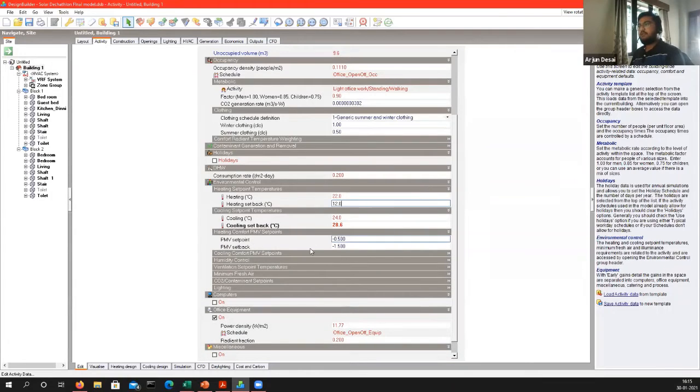The comfort set point: if you are aware of the different thermal comfort models, such as predicted mean vote, you can keep PMV as a set point. Your air conditioning set point won't work at that time. The set point that will come in is the PMV set point.